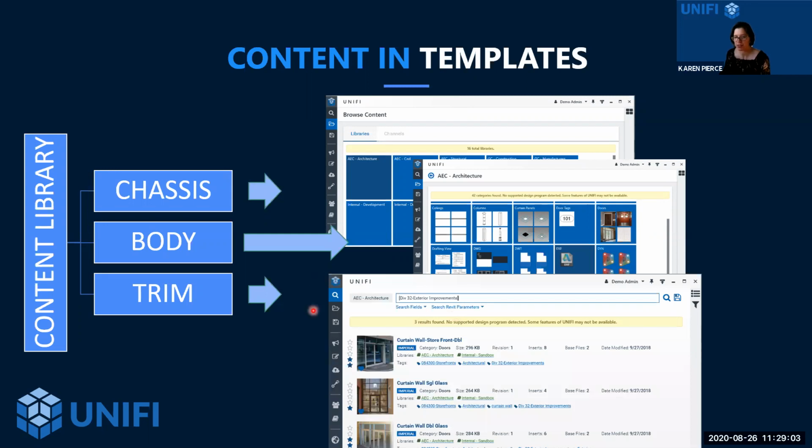And then last but certainly not least is trim. So we're able to not just, hey, we pulled open a category, this is the curtain panels, for example, but I can actually click on the name of this and review items like my parameter data, my types. So it really keeps all of that bloat out of my template now. I can focus on those annotations like we talked about and load the content itself as I need to.